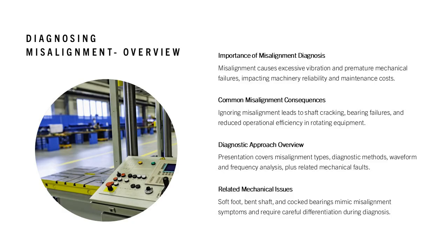This presentation will systematically cover all relevant misalignment types, real case examples, diagnostic techniques, waveform indicators, frequency domain symptoms, and applicable standards. It also introduces related issues such as soft foot, bent shaft, and cocked bearings, which often mimic misalignment symptoms and require careful differentiation. The slide sets expectations for a technical, engineering-oriented session with diagrams, fault signatures, and a flow-based diagnostic